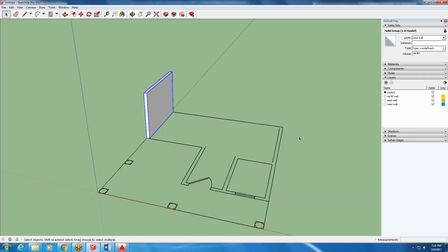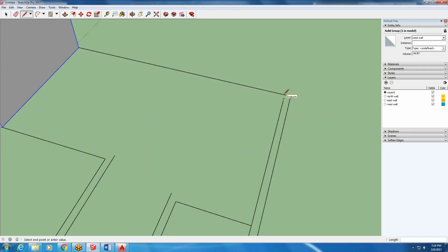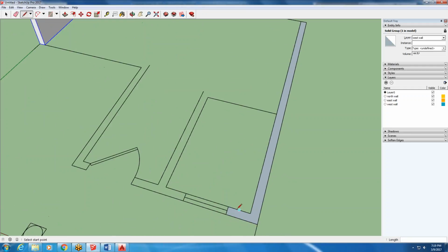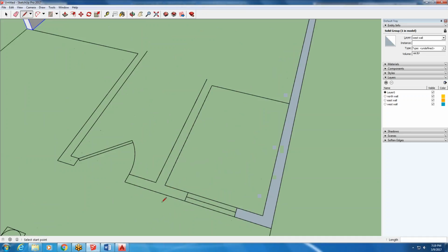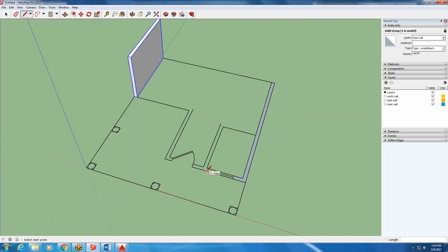Okay, so you could continue. That means though, if we were to draw this wall, remember we got to delete off this little horizontal because otherwise it's going to fill in this whole L. Watch. I'm closing a loop that it already knows exists, and it finishes my L. I don't want that. So remember to delete this little portion here. Be thinking about the horizontals that are going to want to finish your loops while you do them.